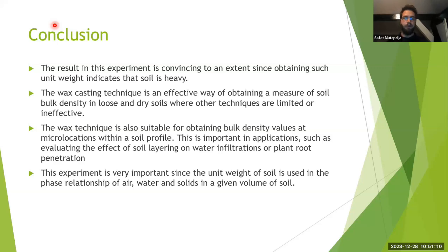So every soil you can compact, right? But there is a specific water content. When you get to that water content ratio in your soil, your compaction is easiest and maximum. CBR is going to define what the maximum compaction is.